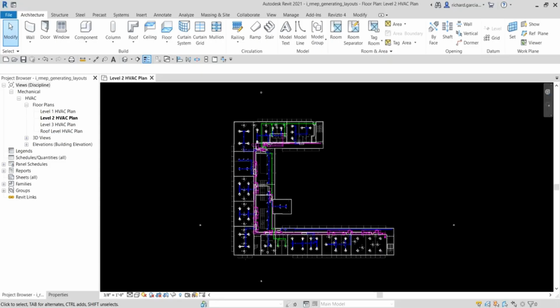Automatic layout tools provide multiple layout solutions such as network, perimeter, and intersection. You will be able to see that later on. These layout solutions, you can explore using the previous solution and next solution options on the options bar. I'm going to show you that later on. If you do not find the required set of connections, you can manually modify layout solutions, which most of the time happens. So after you generate the automatic layout, you can still modify it manually.